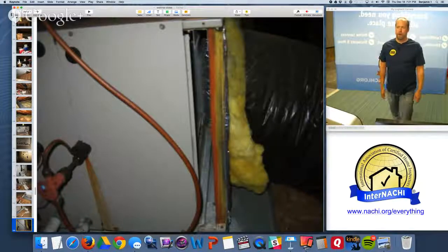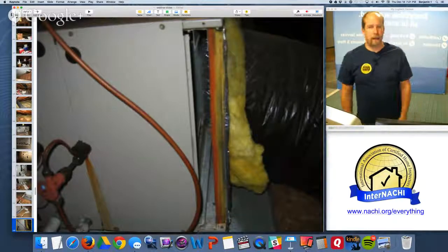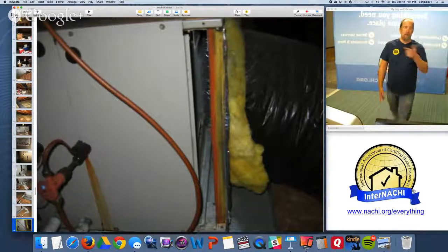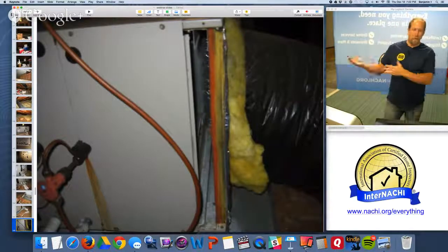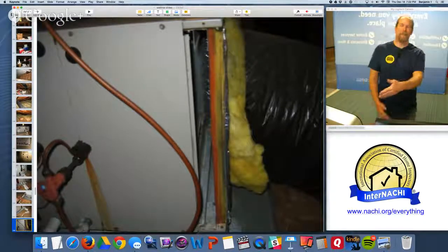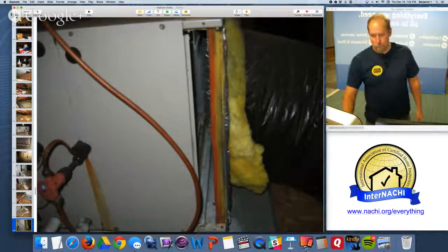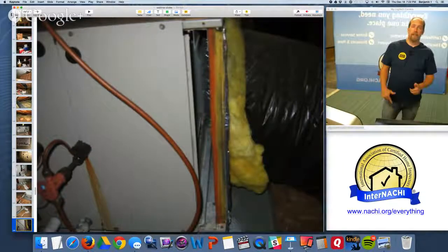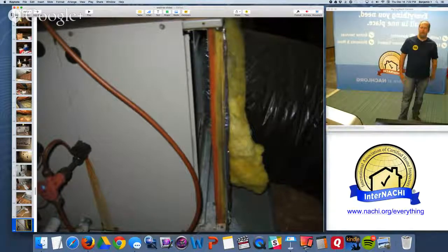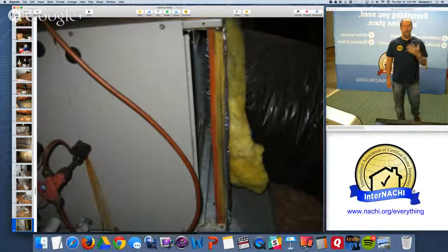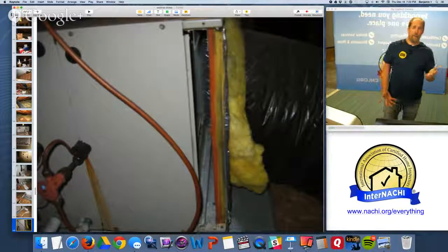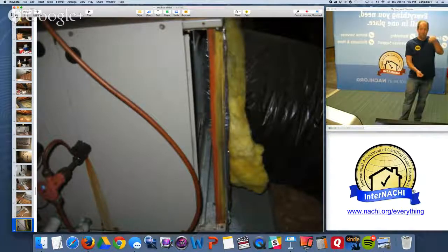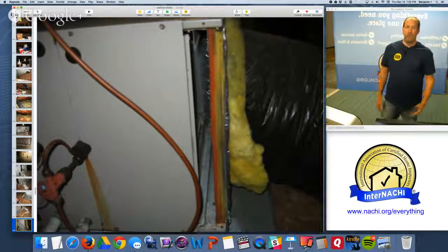Incredible. So I don't know what happens in the hot summertime, but essentially there's no circulation of interior air into that unit. It's all being sucked from the hot attic space in the summertime right into the evaporator coil if it's open like that. And we have partners that provide air filters, really good stuff, and also covers. So you can advise your client about covering the open air filter slot, even if there's an air filter in it, with a metal manufactured cover. It really can be sealed up. It really should be sealed up to be energy efficient.